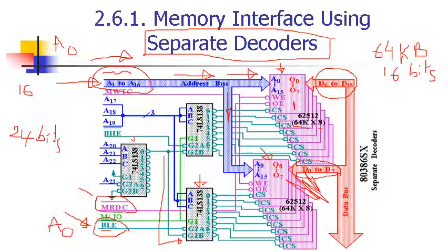If now you're sending 3 zeros, they come to here because this is now active, while your bus high enable could be active or inactive. Let's consider now it's inactive. The signal sent to this is 1, and we are dealing only with the lower bank of your memory. So these 3 zeros will come here. This decoder is not active because BHE is high, making these 3 zeros go down and start accessing memory locations inside your lower bank.